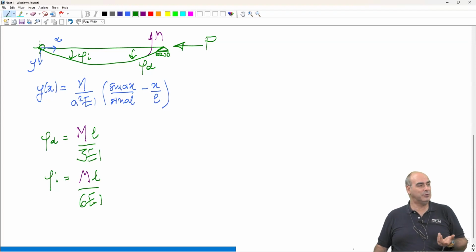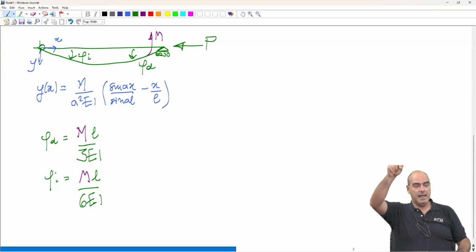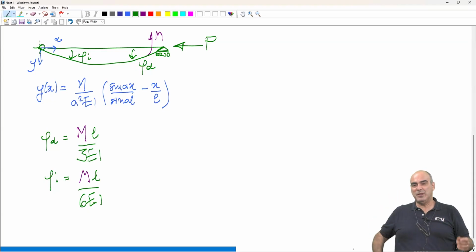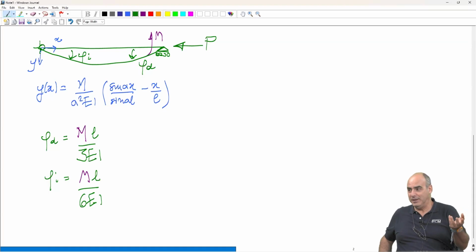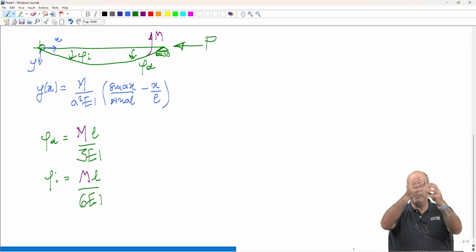Then what about the rotation here? Because, okay, I understand if I have a column and it displaces on the top and I can have the buckling load. But what is the engineering interest of calculating a rotation here? Of the joint, exactly. Those hinges, those joints that I have schematized there, they can be a bottom joint, they can be a beam column joint.